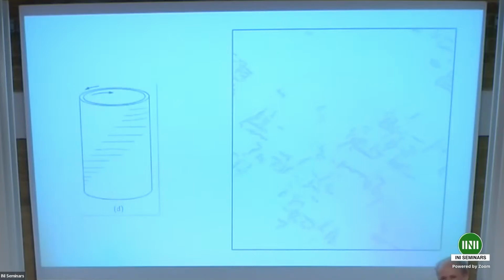I'm not sure I'm answering it quite the right way. But if you did not include that, there would be very, very slow decay back to laminar flow around all these patches, extremely slow because viscosity doesn't act on these constant vertical modes. So you have to introduce something that damps them.